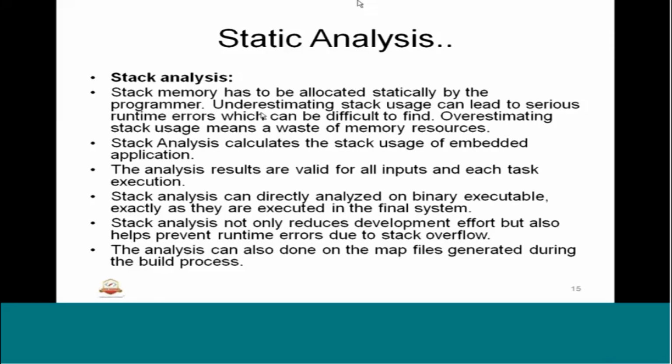So that is why there will be a hard requirement saying that at least 50% or let's say 75% of the stack memory should have a reserve. That means in the worst case it may exceed, so on the safer side we should reserve 75% of the stack, so that if the program spills beyond 25%, it's still safe, because the embedded system will not crash because there is no stack issue or stack error.